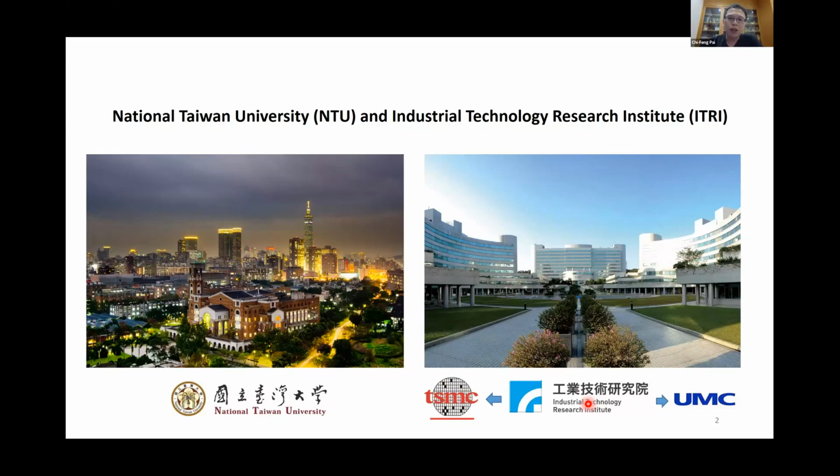Because typically, to make a full SOT-MRAM on their 8-inch wafers, starting from the thin film deposition to the patterning and etching processes and to the final device, it will take probably 2 to 3 months. So we wanted to see if there's any possibility that we can see some early results before making those films into devices.